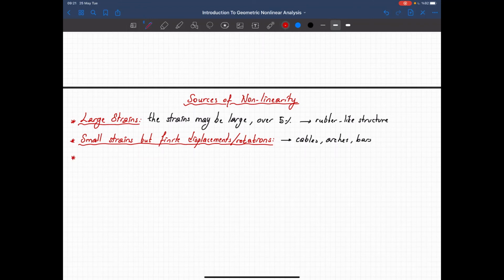Or you can just want to consider the buckling effect, right? The effect of the loads changes due to the deformations. When you have compression and the compressive forces couple with the bending deformations, they tend to increase the moments in your structure, and if the internal moment cannot resist the moments due to the compressive forces, your structure buckles. This may be the only effect that you want to see, and you perform a buckling analysis for that case.